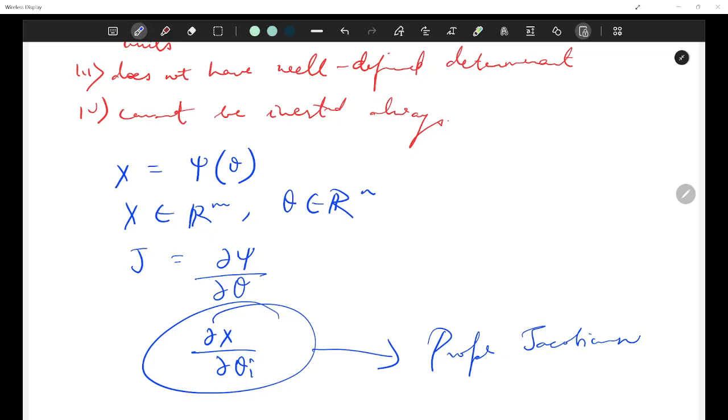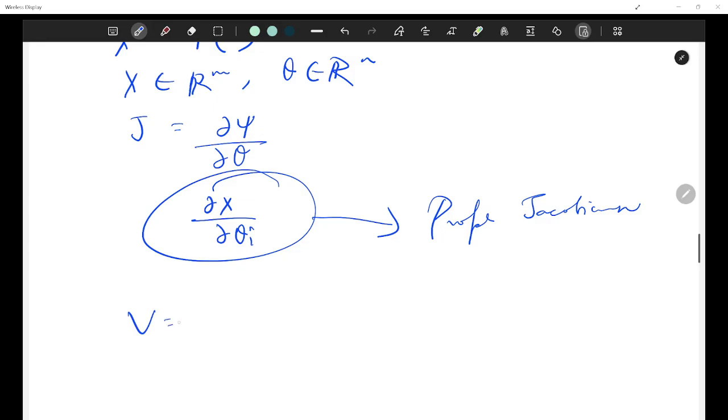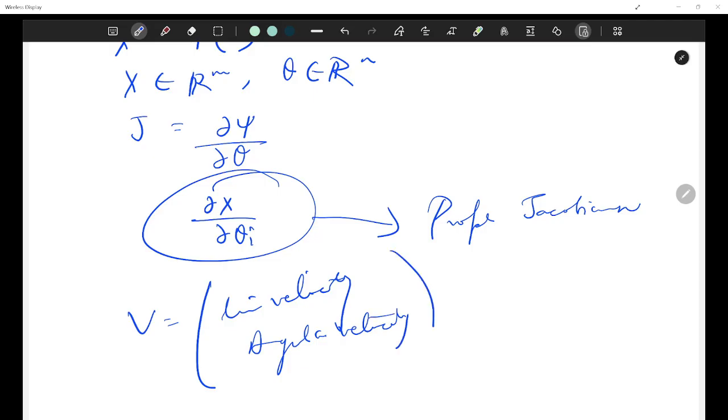What is a manipulator Jacobian? In this, we don't do this, it is different. We define linear velocity and angular velocity. So v is equal to J(theta) into theta dot. That is the whole concept of J. This is not derived by differentiating a 6 cross 1 vector function (x, y, z, alpha, beta, gamma), because angular velocity is not the time derivative of the orientation parameters. It is not alpha dot, beta dot, gamma dot. Instead, omega is extracted from R dot R transpose. Thus, a spatial manipulator Jacobian is constructed from velocity propagation, cross products, and angular velocity relations, and it is not obtained from direct differentiation of x, y, z or the orientation parameters.